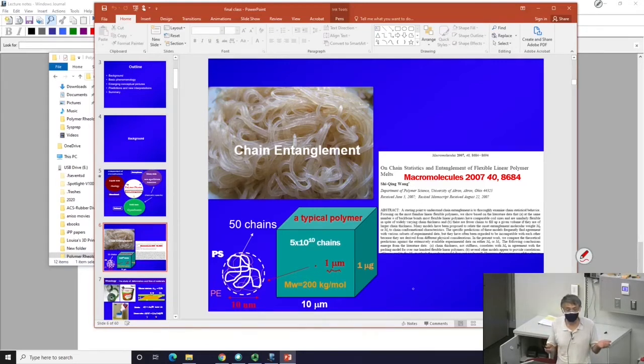We all need to acknowledge it has the ability to move around, typically because we're dealing with it above Tm and Tg. And it becomes more difficult to move around as you approach the so-called glass transition temperature. And it becomes more difficult to move around if the chains are longer.